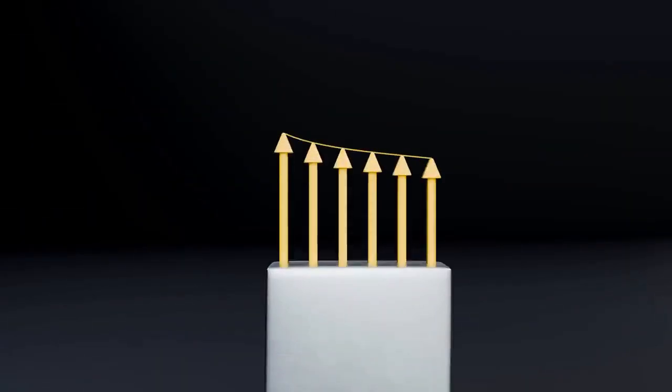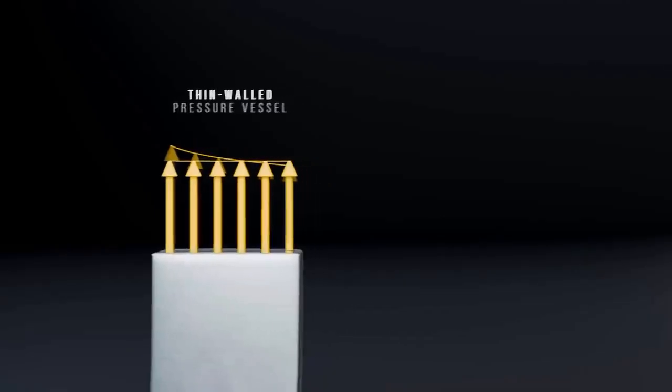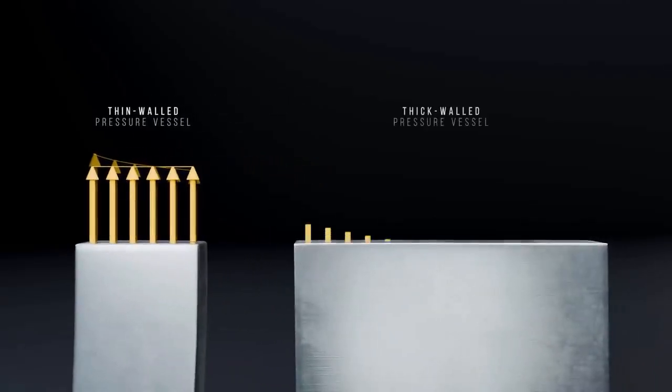The vessel wall shown here is thin relative to its diameter, so the reduction in hoop stress is small, and the assumption that hoop stress is constant through the wall thickness is reasonable. For thick walls, though, the variation in hoop stress becomes too large to ignore.